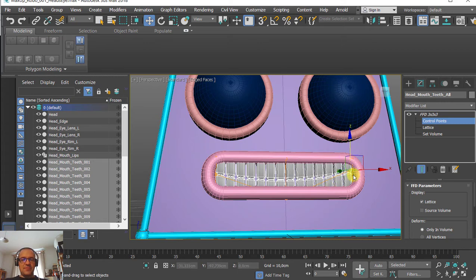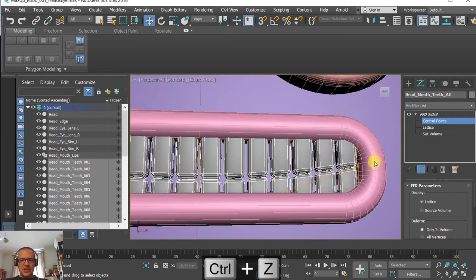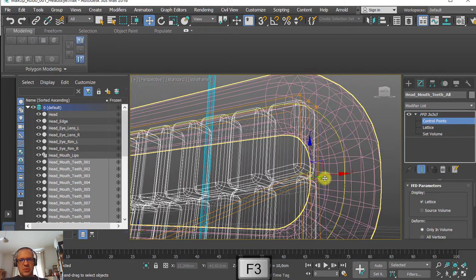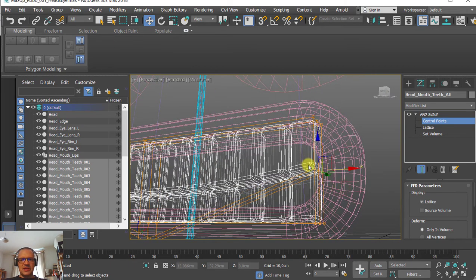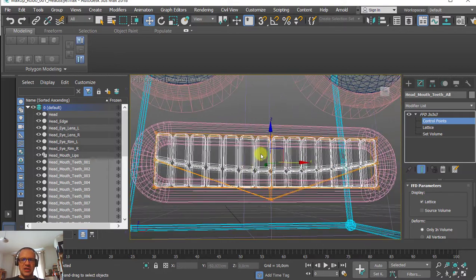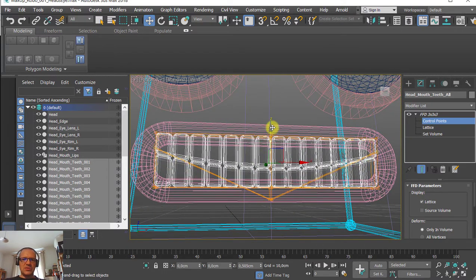But hey, issue here. When you are selecting these points, you always should use a window selection, because if you are just clicking, that can only select a point. Alright? So select these, and I'm walking on the other side, holding down Control because I want to add these other 3 points to my selection. And now I will be ready to do this. And guess what? I've just moved it.